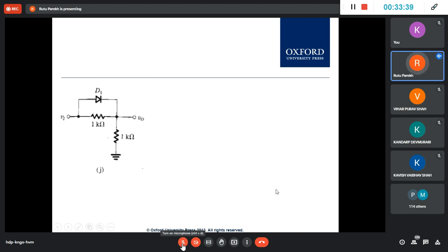Okay, now this is a good example, and whosoever will try to help us, you will write your ID in the chat box. Now, here also you can see two resistors and a diode in parallel with this 1K ohm resistor here. And you start with the positive half. The positive half will pass through D1. Current will pass through the less resistive part.